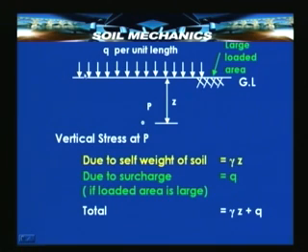Now, as long as this loaded area is very large, somewhere near the center of this loaded area, the point P is going to experience a stress which is equal to this Q itself. This is actually valid only if the loaded area is sufficiently large compared to the area within which we are trying to determine the stresses.